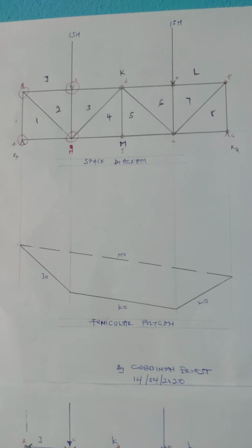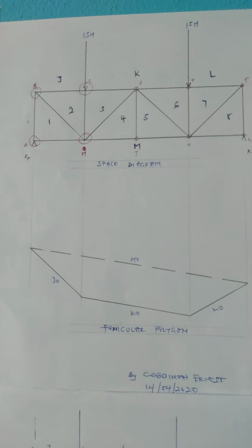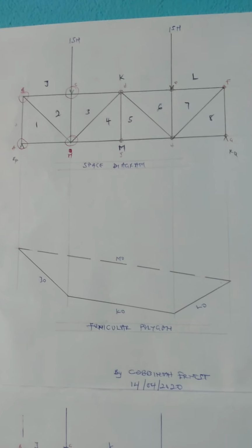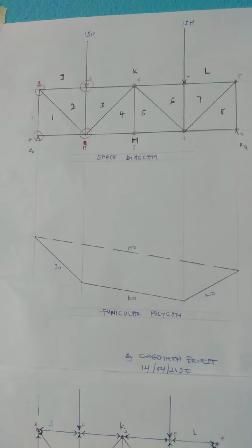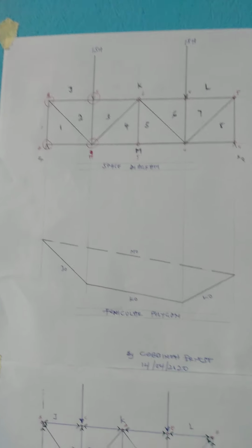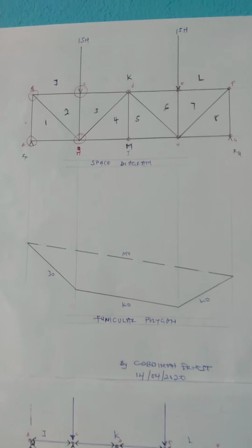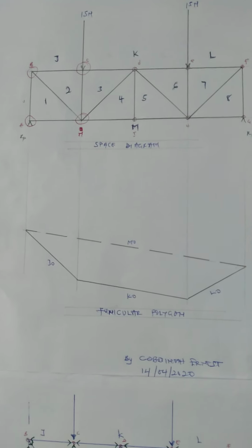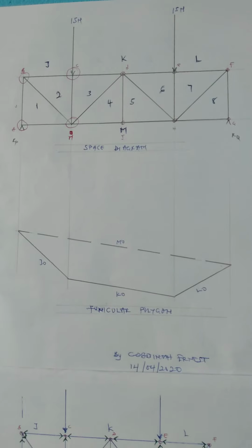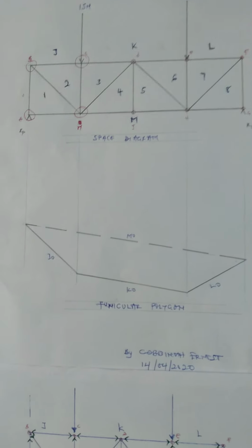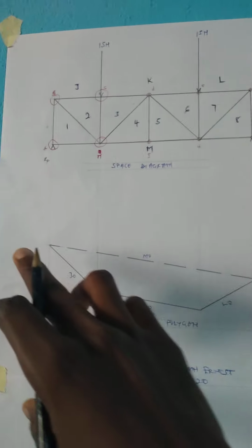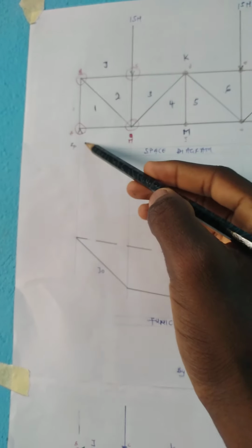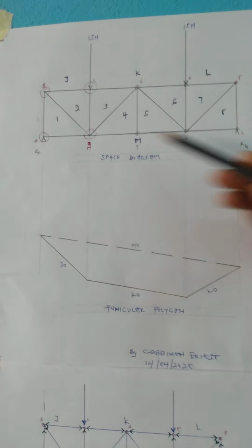Now, this is a truss that I think we didn't work any example on before you left. So it might seem a little bit complicated to you, but the procedure still remains the same. Now, this truss is mostly seen in bridges, unlike roofs. They are used in bridge construction and it is a simply supported truss because the reaction supports are at the various ends of the truss.